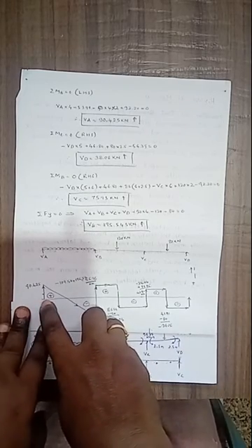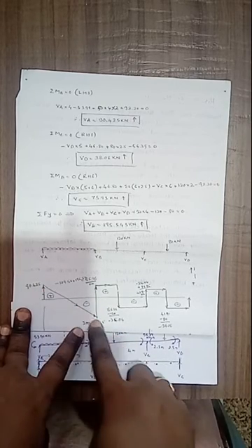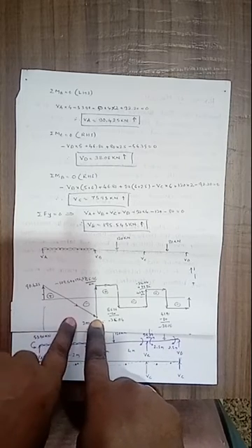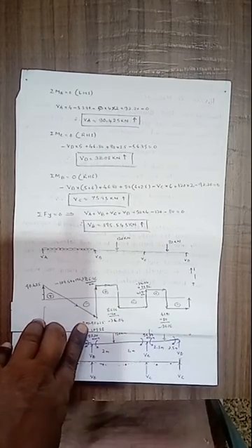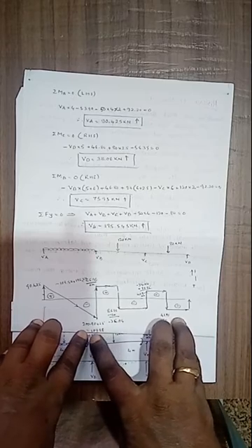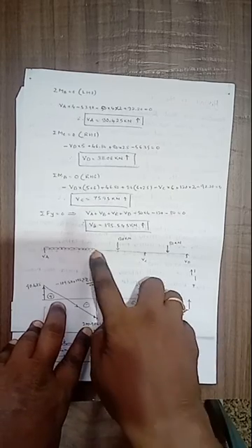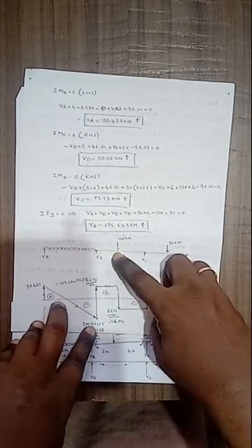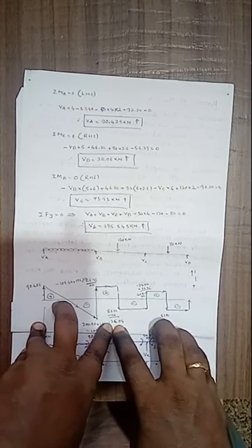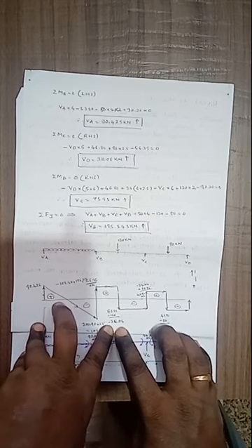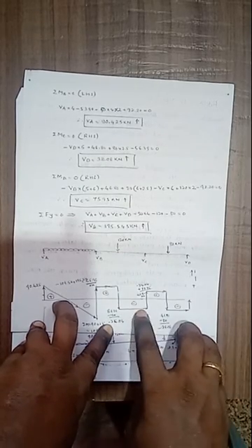Here the variation of the shear force is, here this one is upward, and then because of this UDL the shear force decreases gradually and it is a straight line. Then here there is a support reaction VB. Due to this the shear force changes from minus 109.58 to 85.96. Then here it remains constant from B to this point load, then that is positive 85.96 minus 120, this one is downward, then that becomes minus 34.04.